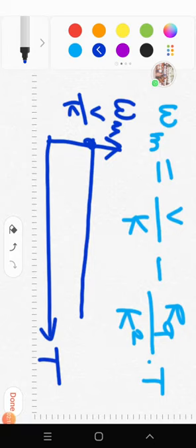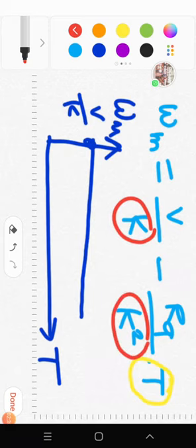So we know that torque is not in our hand. We cannot change the torque because it is the demand of the load. And this K, motor constant, also we cannot change. So only variation possible is we can change armature circuit resistance and armature voltage.